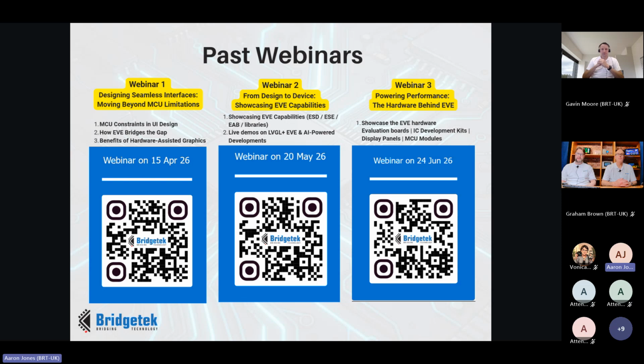For example, in the Eve MCU Dev implementation, we allow the attaching of a folder which represents the files on your SD card. Similar to what I just mentioned previously, the emulator DLL also allows the functionality to support SD card images directly as well. We haven't implemented that because we find in MCU Dev it's easier just to create a folder, call that SD card folder or whatever the name happens to be, and put all your assets in there, and then that will be attached in the emulator projects.